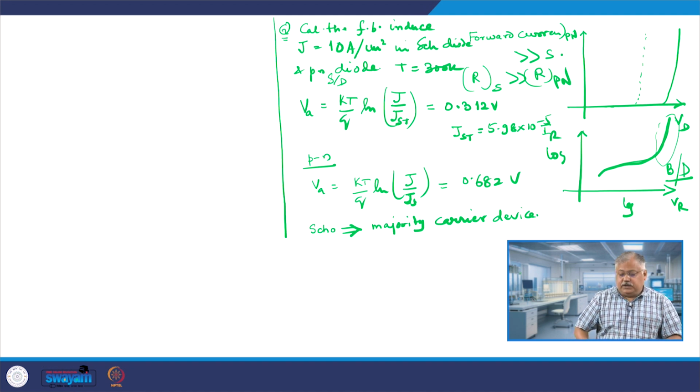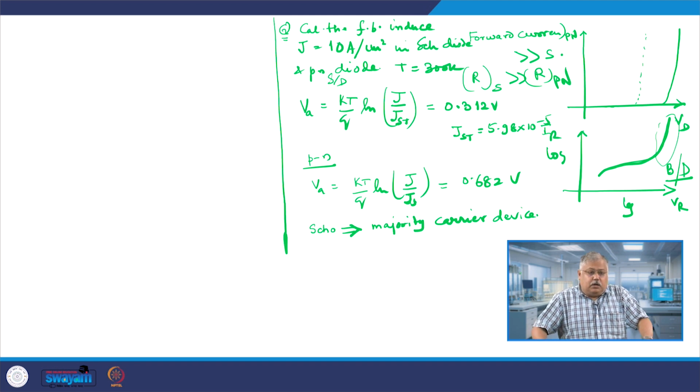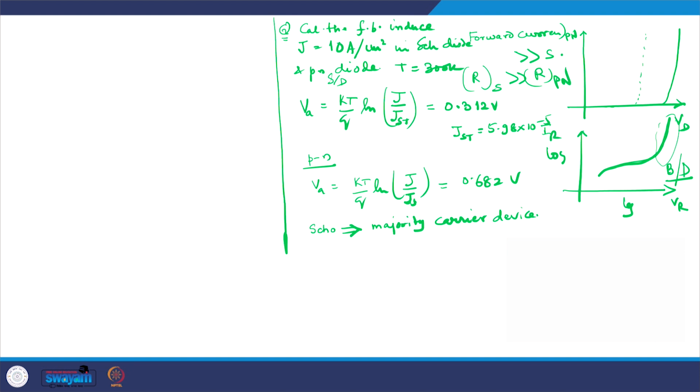However, there is an issue which I have left while discussing any type of device here, and that is basically the switching characteristics. Now, a Schottky diode actually works at a much higher frequency than a p-n junction, because the switching speeds are relatively higher, and the reason is that you will have minority carriers to be removed in a p-n junction diode when you switch the voltage in order to have a fully depleted region. That is not true in the case of a Schottky diode, and therefore the switching speeds are much faster in Schottky diodes as compared to p-n junction diodes, right. It is relatively much faster to carry forward with it.